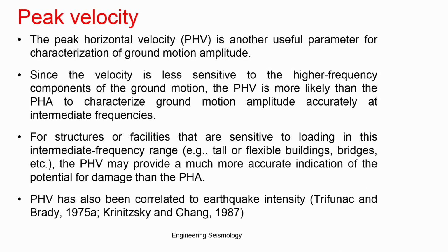The PHV has also been correlated to earthquake intensity by several researchers, where you can see how particular structures got damaged, and how much percentage got damaged with respect to PHV. So, whenever you have this kind of tall structure, flexible building, or bridges, acceleration is basically meaningless. You have to consider the velocity data and the peak horizontal velocity for the design.